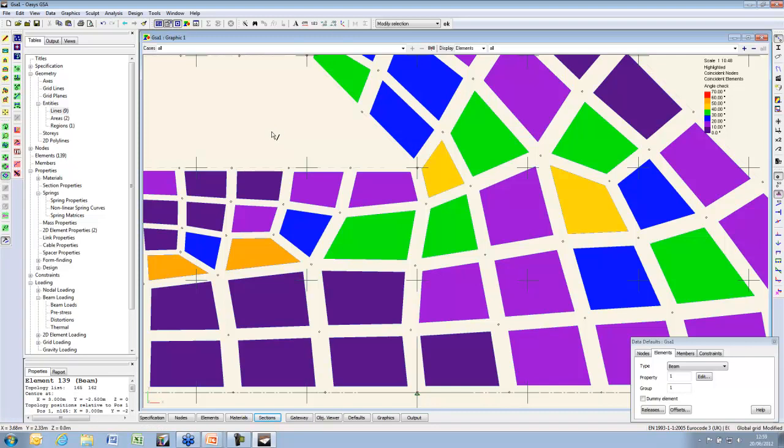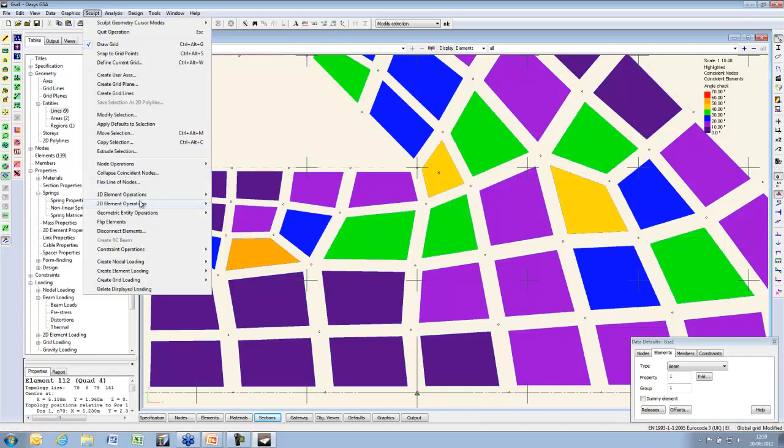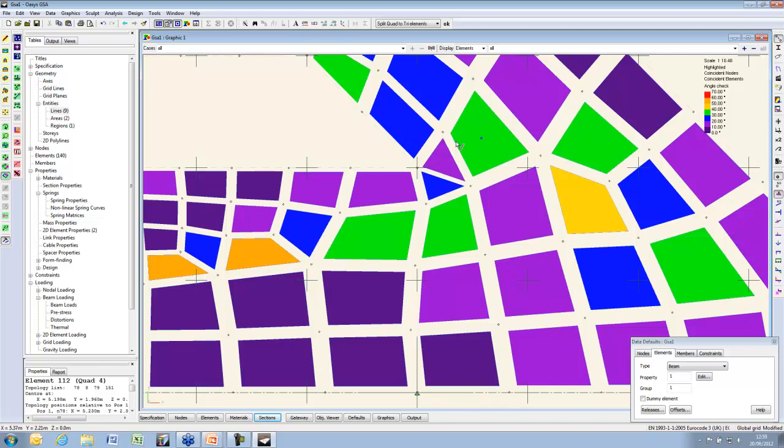If you create a manual mesh, or if you're in a real hurry, there is a trick. If I select that element, there is the option to split quads down to triangles. Because triangles are much happier with sharp angles, this will take the largest angle and draw a diagonal, and you'll end up with happier mesh elements.